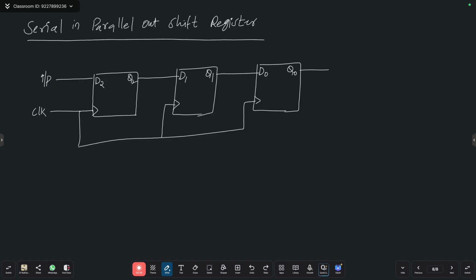We have 4-bit register. Here, how many bits I want to transfer in this case? I think 3. So 3-bit shift register. So these are the 3 flip-flops. Okay? Right. If we transfer n bit, we need n bit shift register, means n number of flip-flops are required. Correct?